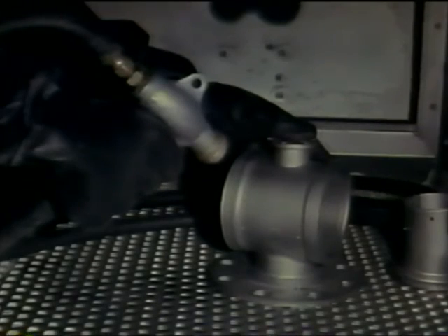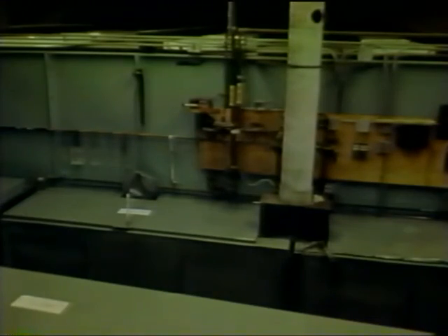The rework and bead blast of the hub and its components are the final steps before plating and assembly. Bead blasting utilizes small glass beads shot from an air gun. This process will remove all traces of scale, corrosion, and foreign materials. All parts of the hub manufactured from ferrous metals are cadmium plated. This plating offers the maximum protection against corrosion in the elements. Cadmium plating is done in this room. Precision instruments are used to monitor the process, and the solution is tested for purity at regular intervals.